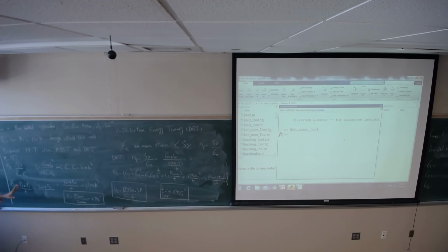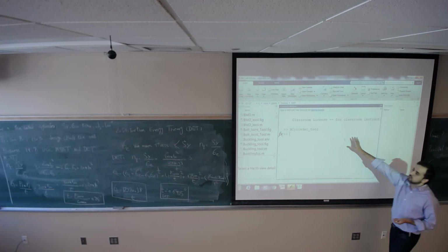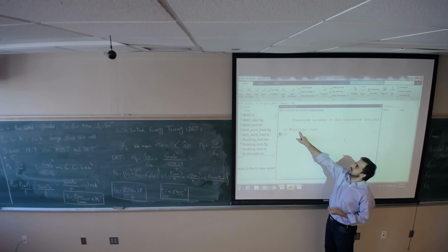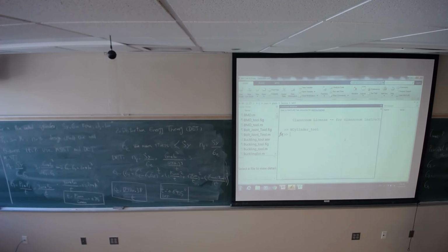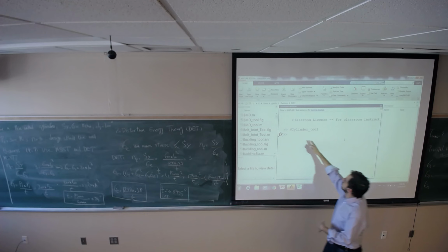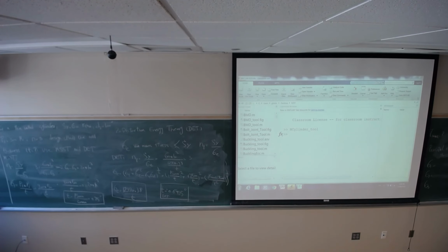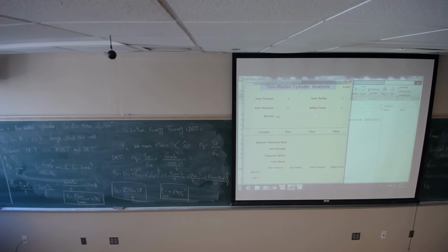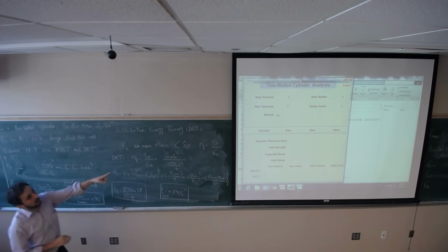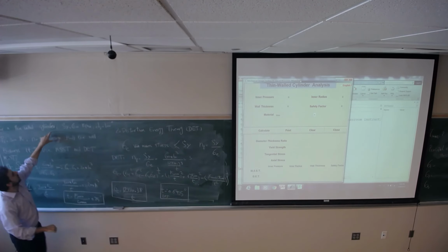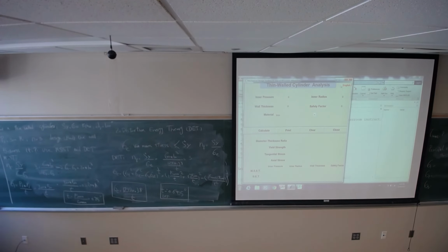All right, let's look at the toolbox that you are supposed to use, representing thin cylinder on line 2. So capital N, capital C. If you type, it's gonna bring this. On the very top line, you can see English units. So here we don't have SI, we have English units. So I check mark this.